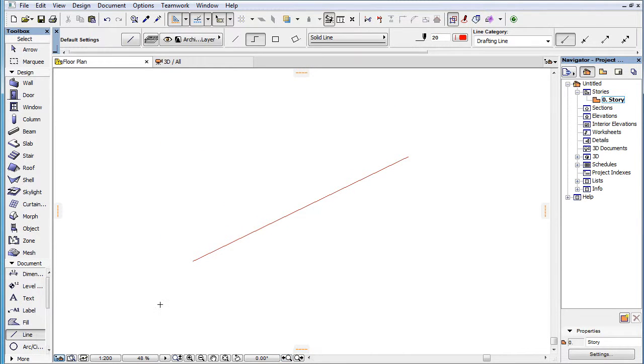When the starting point of your input falls on a straight edge, the edge is implicitly considered marked as a snap reference. This way, you can easily find the extension line of the edge and the perpendicular direction to the edge from your input point.